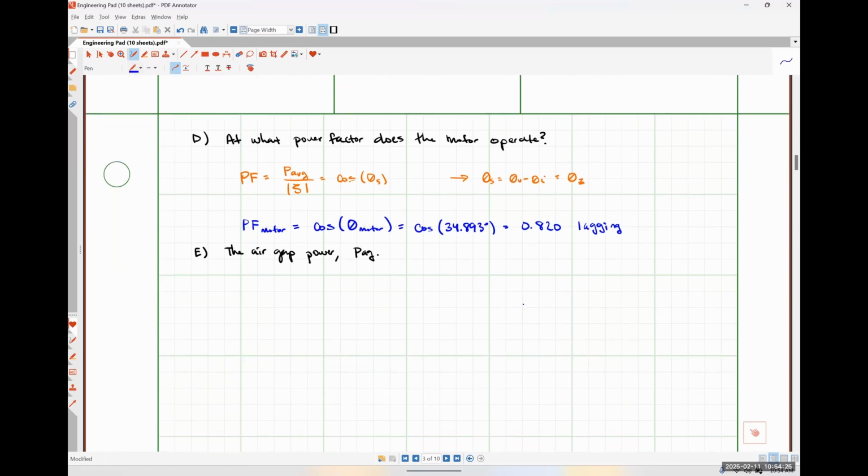So this is just another application of an equation that we covered last week, and I reminded you all of what it was earlier today. So I'm literally just going to write this equation down. 3 times the magnitude of our Thevenin voltage, which we already determined in a previous step, squared, times R2 prime over S,